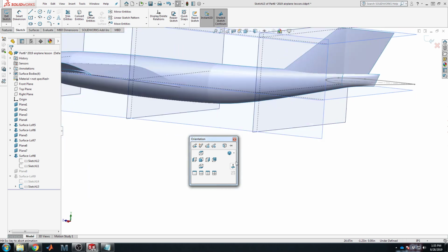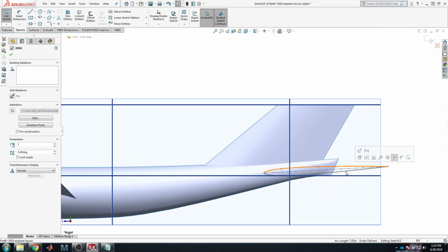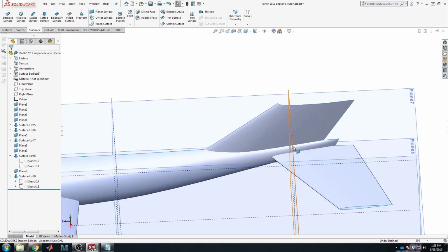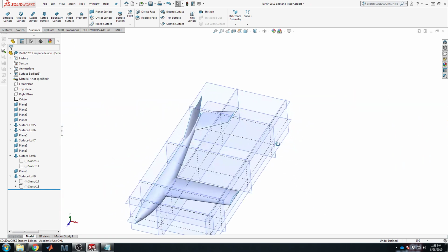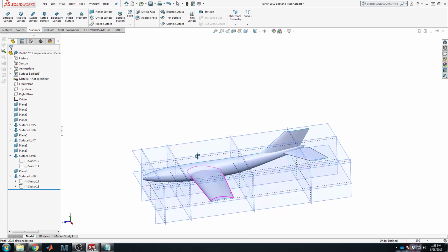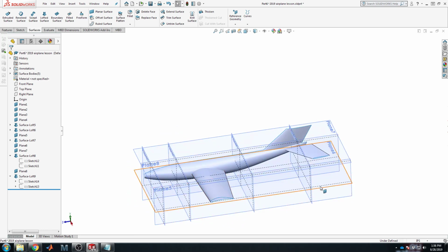Easily done. Just go back into the sketch for the root, click on your block, change its size there. I don't know, 5? It's swept, but that'll make it look cool for now. Hard to build. I would not recommend doing that on an actual airplane. Like, keep your horizontal elevator with a straight hinge line. But anyway, that's now going to be kind of half the airplane.